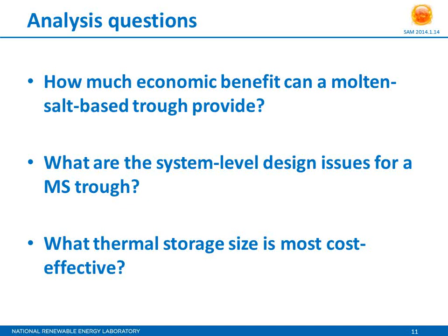What are the system level design issues for a molten salt trough? Like I said, freeze protection, how do you lay out the field? What does that look like? What kind of things can we do to optimize that? And finally, what thermal storage size is most cost effective? That's a question you can answer with the parametric analysis in SAM, and we'll cover that at the end.